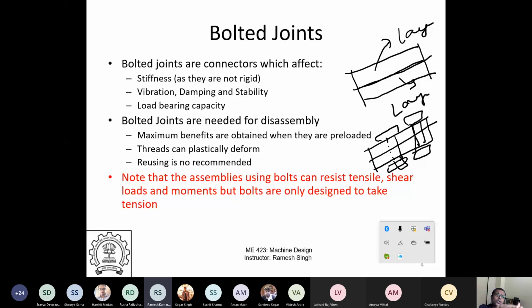So I basically somehow bond the two layers. So there's perfect bonding, and there is contact by using two bolts. What is the fundamental difference between these two kinds of joints? Now, permanent and temporary is fine. Functionally, I'm asking. Agreed, it's a permanent thing. I cannot disassemble. But functionally, how different will it be? What will be the difference between the two? Is there an advantage of having a perfect bonding other than assembly and disassembly? I'm talking about functionality.